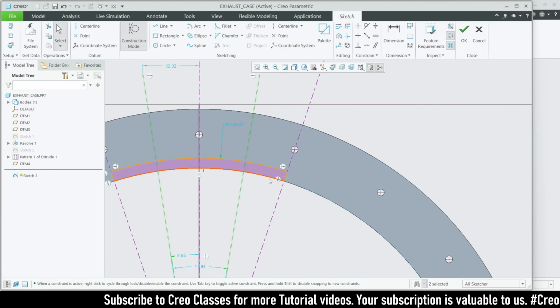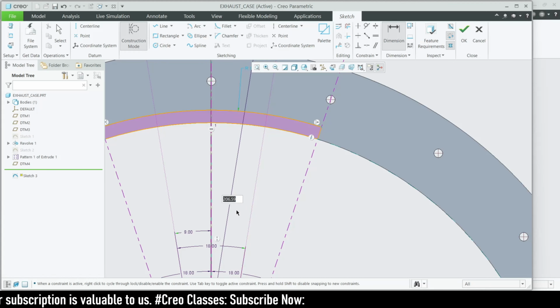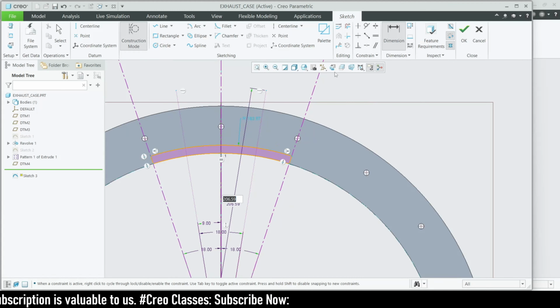So this angle I need as 9 for the midpoint, and this angle I need as 18. If you select this and this, and go for dimensions, from here till here it will be 9. Okay, we have found the center point. I'm going to delete this. Center point. I'm going to unclick this construction mode, and now we can divide this sketch.